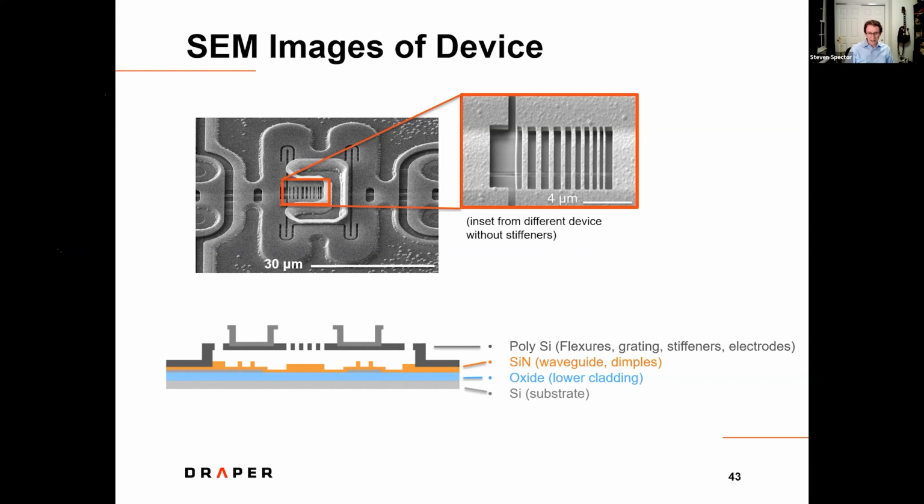It's electrostatic actuation. So it's actually a good drawing to pause on. Basically there's an electrical connection to the top and electrical connections to these pads below. There's a pad under here and a pad under here, and you basically put opposite charges on the two. You get electrostatic attraction and it pulls it down.